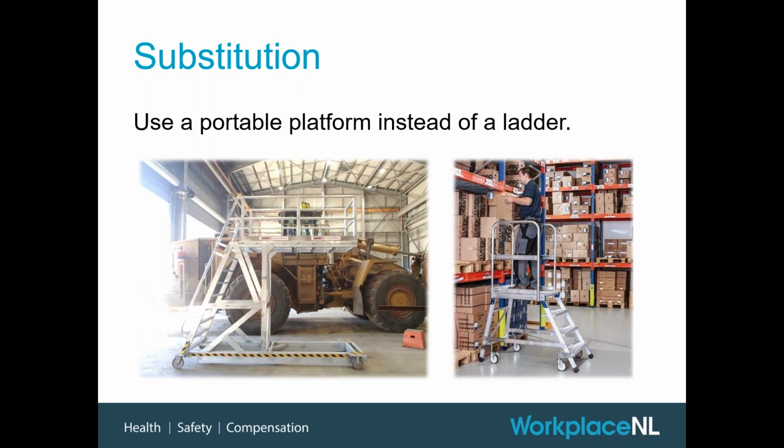These little setups have a set of stairs typically that leads to a platform that has a little rail across it, so the worker can walk up the steps, put the rail across, and then they're now on a secure platform where, again, they don't need to use any kind of fall protection equipment. The guardrail is effectively what's protecting them from falling at that height.